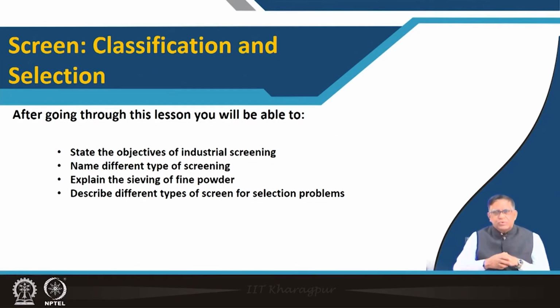As we already told, when the ore is to be beneficiated, you will find the fines play a big role, and sometimes we have very fine material that we cannot separate by sieving, so we need another operation called classification, that is, classifiers are used.